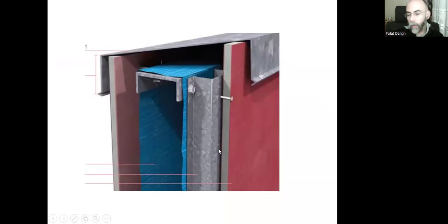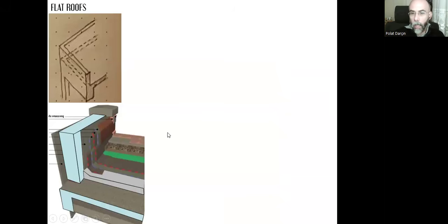And based on your building structure, instead of preferring heavy materials like reinforced concrete or bricks, you can create a parapet wall out of thin boards made out of cement, and you can fix them using nails, sorry, or bolts over this system of steel, and you need to have a coping.